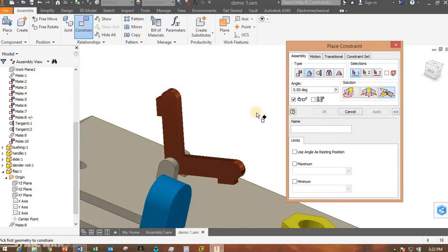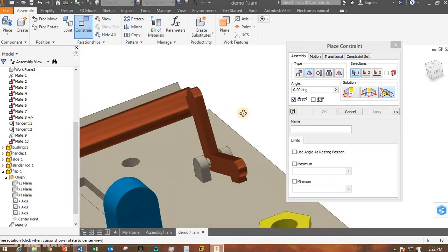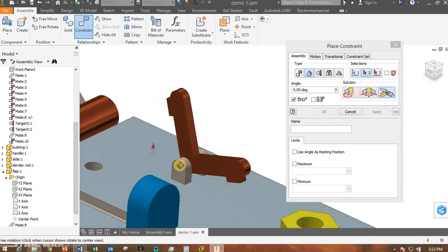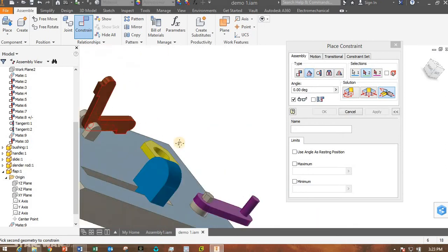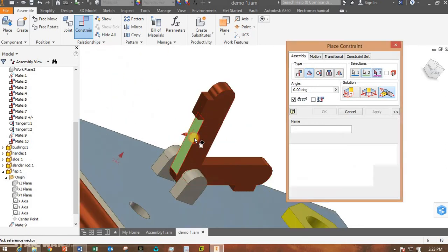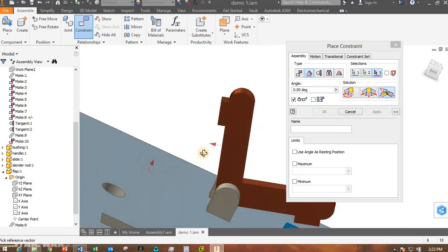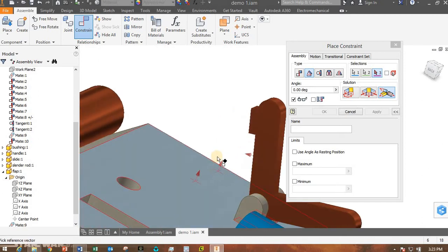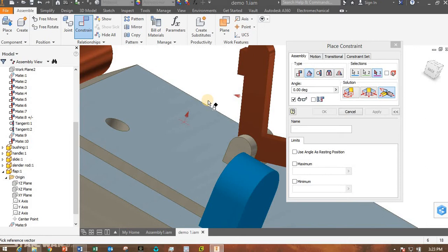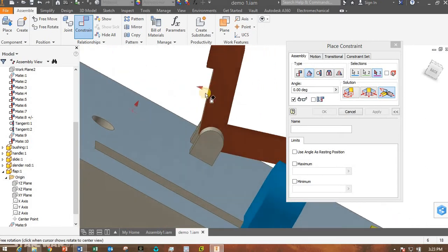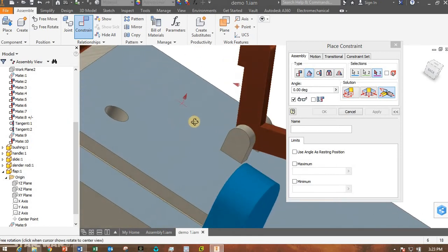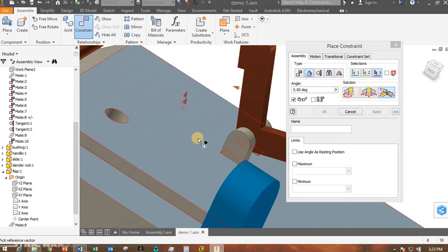So you see the first two arrows are going to be arrows on surfaces that I want to define the angle between. Let's click on this surface, and let's say define the angle between that surface and this one here. But now the third surface that I need to choose is one whose arrow is perpendicular to both this one and this one.